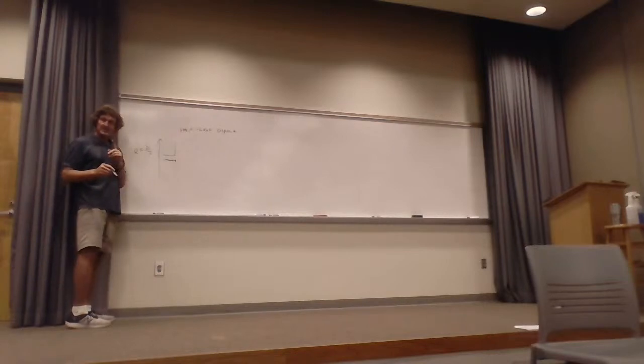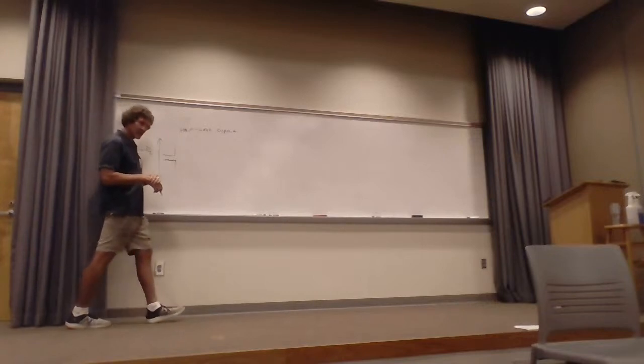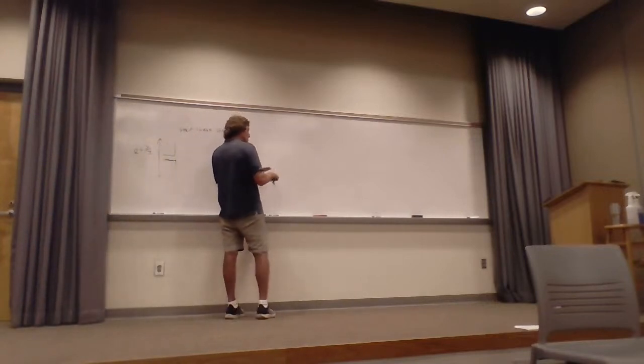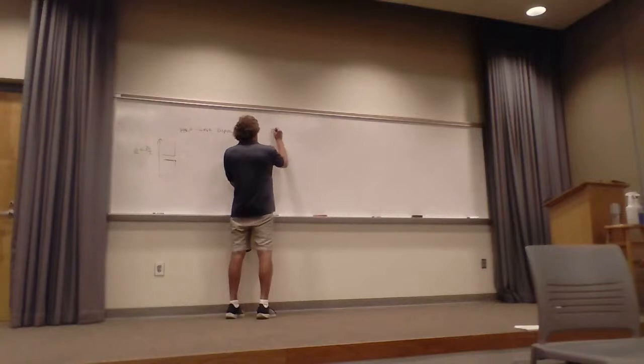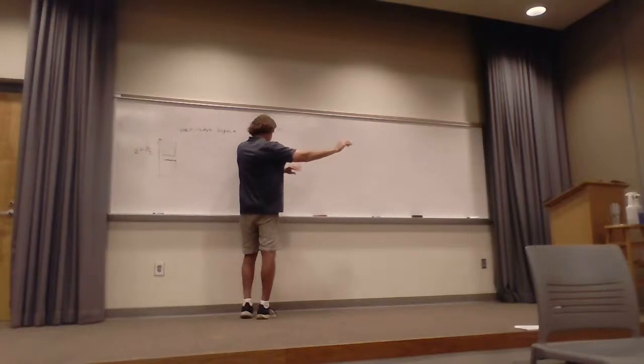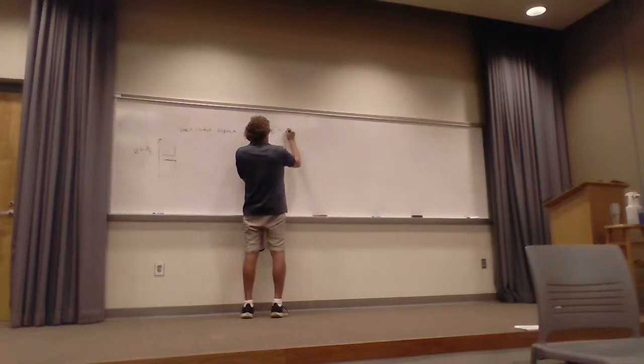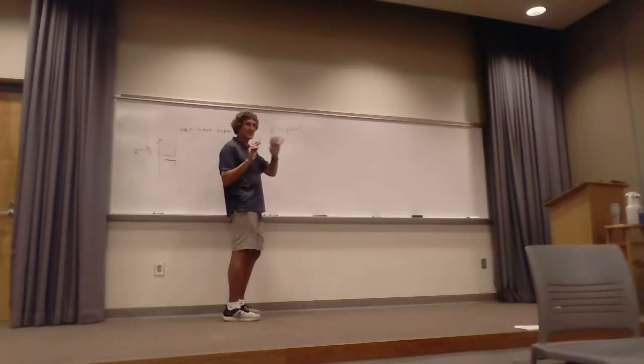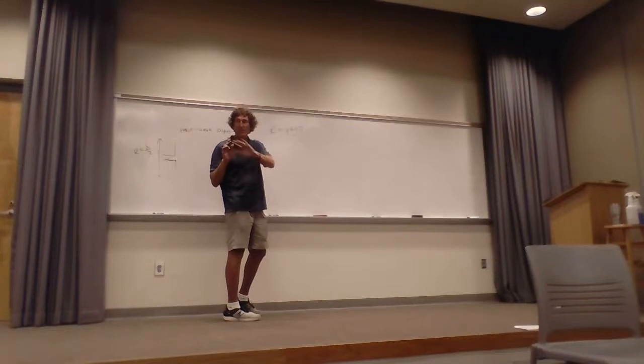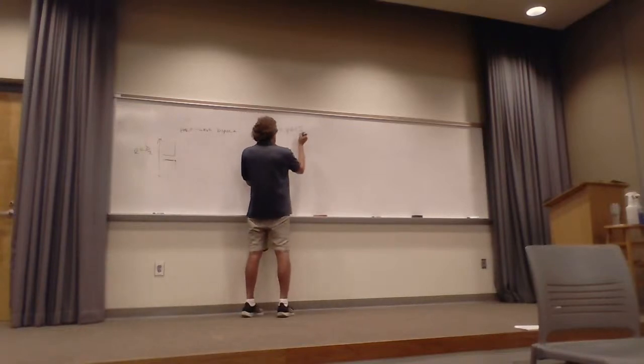Okay. Now this is significant because if the length becomes half wavelength, then when you look at the E field from this, I'm not going to back up and get to the formulas. It will be j times 60I. Just write this down. I got rid of the 2 pi's. I took the eta beta and got rid of all that junk. It's just 60I over R, and R is the radial distance.